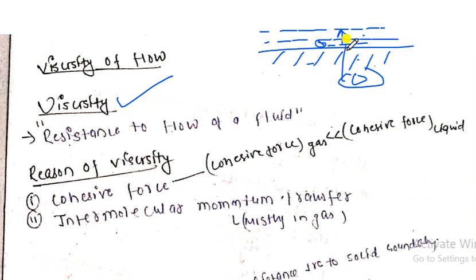Suppose, imagine this one is a solid body, right? If you keep water on it, then the water starts flowing even with a small force, right? If we put water on this and then the water starts flowing, then my dear friends, the water which is in contact with the boundary layer feels more resisting force, right? Here the flow of liquid is very less, the speed of flow of liquid at the boundary layer is very less.